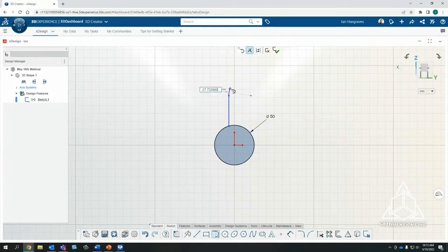For Solidworks, I can also do the tangent curve. So hitting back on that line, I can switch between lines and arcs. So very much similar functionality that we're all used to. I also have relations. So if I want to make these two vertical, I can just select those two and add them. Again, building it in. Nice thing is it does give me a dimension here, which I actually want to use. So if I just click on that, I can set that dimension right there.